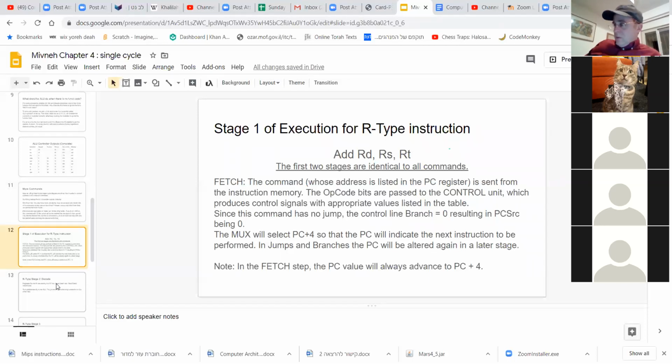But branch can, because branch doesn't do any append. It doesn't stick the PC on the front of the location. It adds to the PC. It does an addition, which means I can take 0FFFFFFF and add 10 to it, and I'll get 1 0 0 0 0 0 0 10. Jump will concatenate the first 4 bits of the PC to the 28 bits of the jump command. It does a concatenation, and whenever you're doing concatenation, you're stuck with whatever you're concatenating. But when you're doing an addition, I don't care if it's 0. Now it's going to be 1.